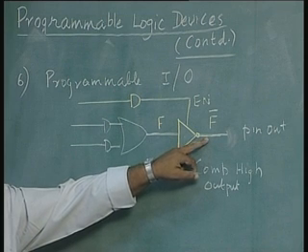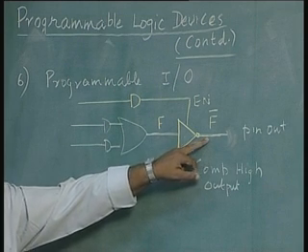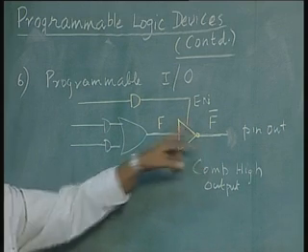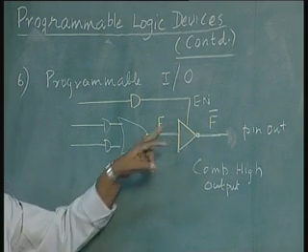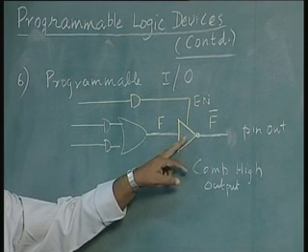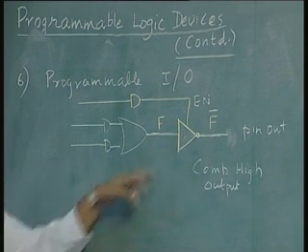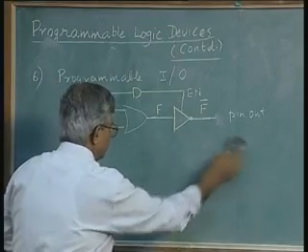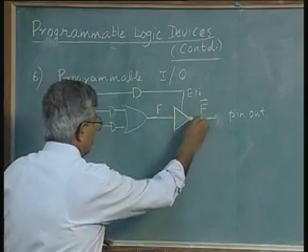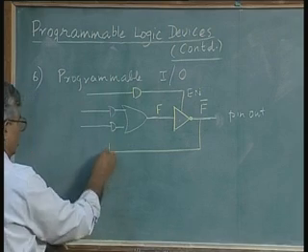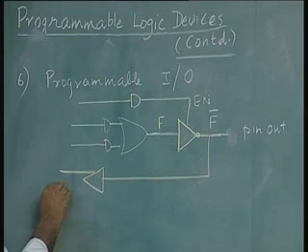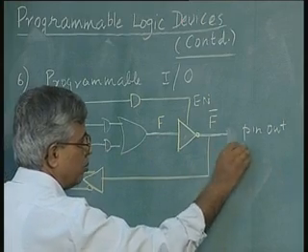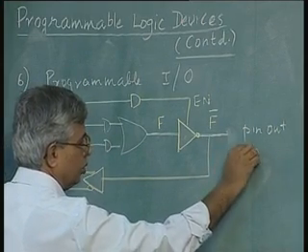So, this high impedance output or a tri-state output means practically there is no electrical connectivity between this point and this point. This point is isolated from this point when you disable this buffer. So, that pin can now be used as an input. I can altogether give some other input. So, in this case it becomes a pin in, an input pin.